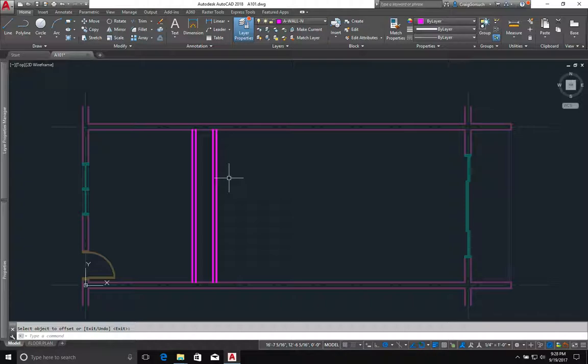So that's any standard interior wall. And sometimes you'll hear partition. There's a little fuzziness on when they're applicable. If you're talking to someone who works in systems furniture, like office cubicles, a partition is the barrier between two cubicles. There's no drywall component in it whatsoever. Whereas for some people, a partition is an interior non-load bearing wall that has studs and sheetrock. So it's a terminology thing, and it's not always clear when one is used and when one isn't. Let's see, what's the next thing?